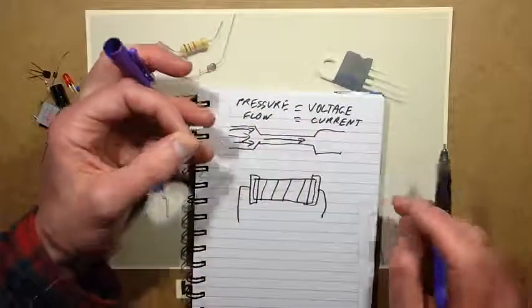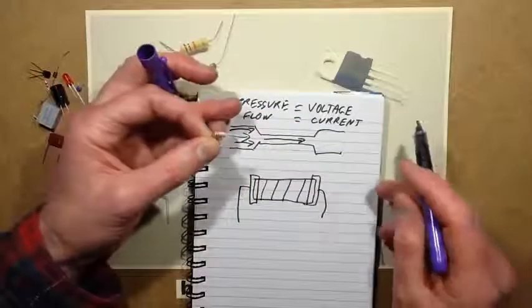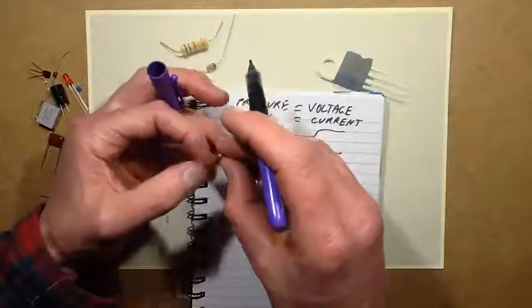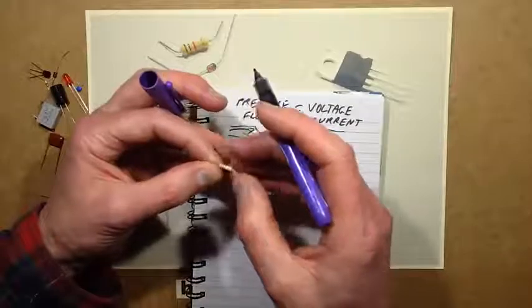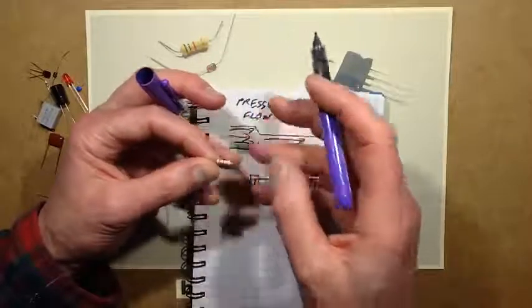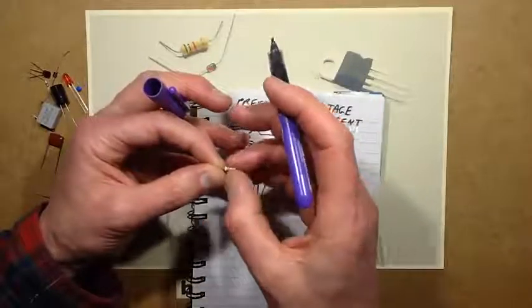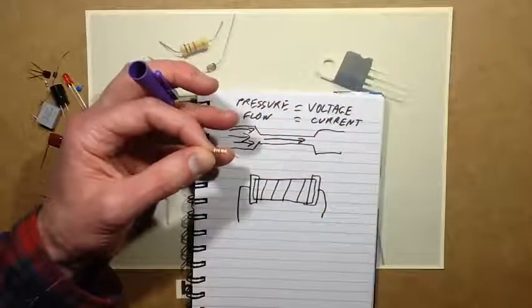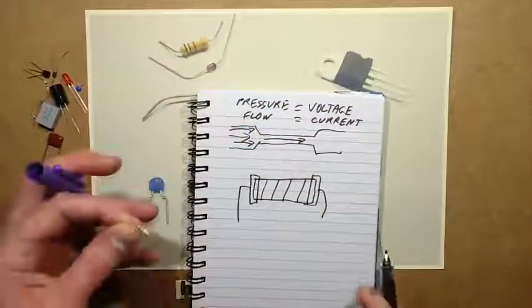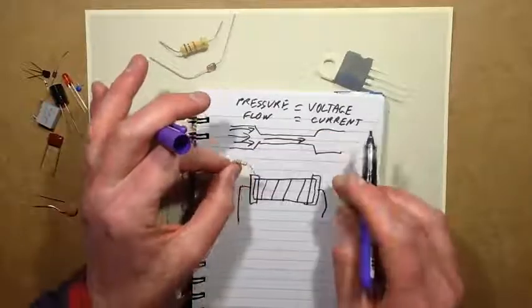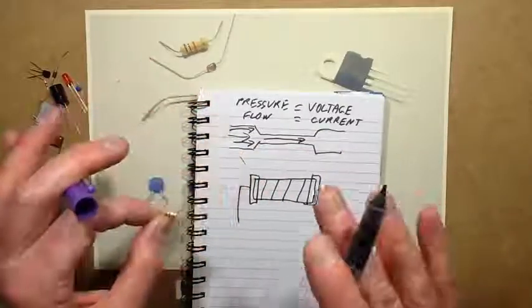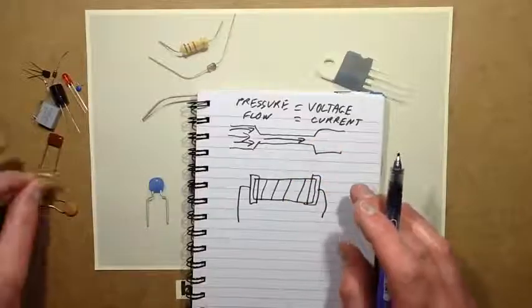And the metal film resistors, which I don't like, because they're usually blue, and they're really hard to read. The blue colour makes it easy to mix up colours like orange and brown, because they've got such a dark background. But I'll go into those colours afterwards. So that's the function of a resistor. I'm not going to go into it too much at the moment, because at the end of the video I'll cover things like Ohm's law, but I don't want to bore the pants off you, so let's move on to capacitors.